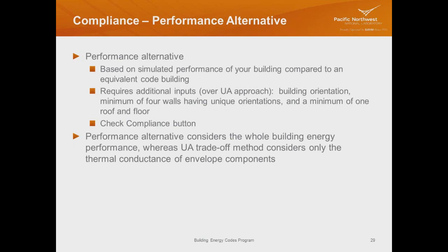And when I say facing, it's so you are standing in your house, facing the front door, and is it facing north, south, east, or west, whatever it might be. That's how you determine it. And we'll play around with this a little bit in REScheck. But if you want to use the simulated performance approach, you would have to do all takeoffs for all your walls and show the orientation and put your applicable windows and doors under each wall.